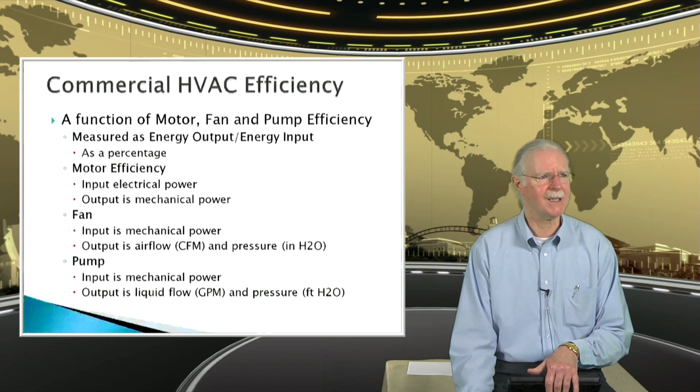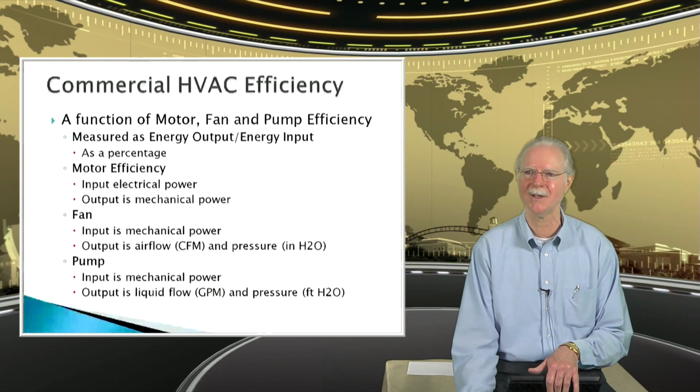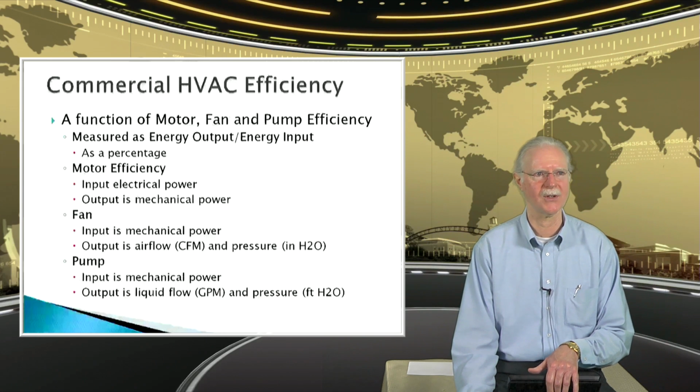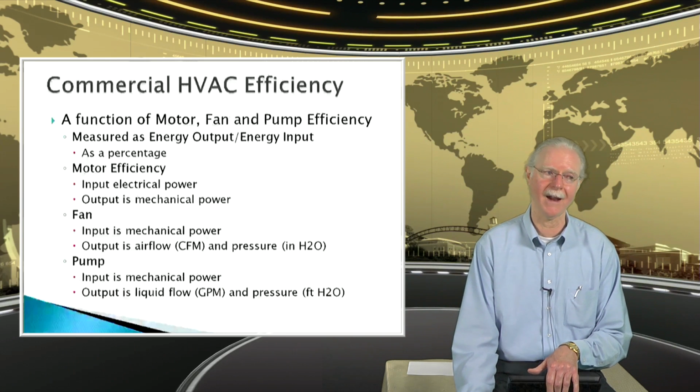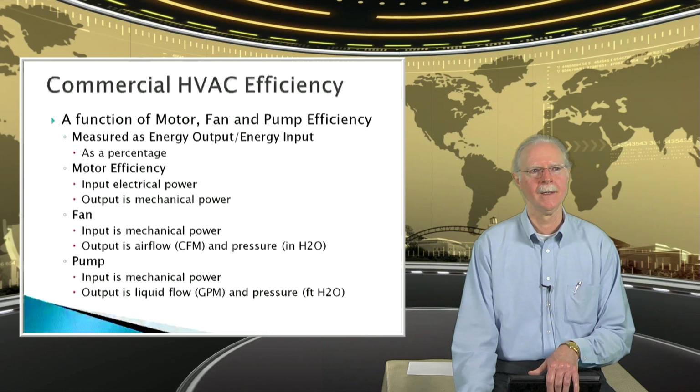But you may have the ability to go back in and say, okay, let's just increase motor efficiency. We can do this as a retrofit within the equipment without spending $40,000 a unit. Maybe we can spend $1,000 a unit to increase motor efficiency. Maybe you can deal with the fans themselves. Is there something about the fan that moves the air that could be made more efficient? Something about blade design or something about bearings that are now worn.